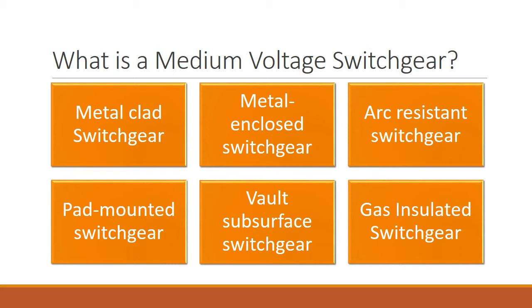Pad-mounted switchgear is appropriate for utility distribution, feeder sectionalizing, and circuit protection applications because of its outside-rated low profile and tamper-resistant design. To protect loads, isolate faults, and reduce outages, switches, fuses, and vacuum interrupters are often utilized. In a shared insulated sealed tank, pad-mounted switchgear with up to 6 ways is actually possible.